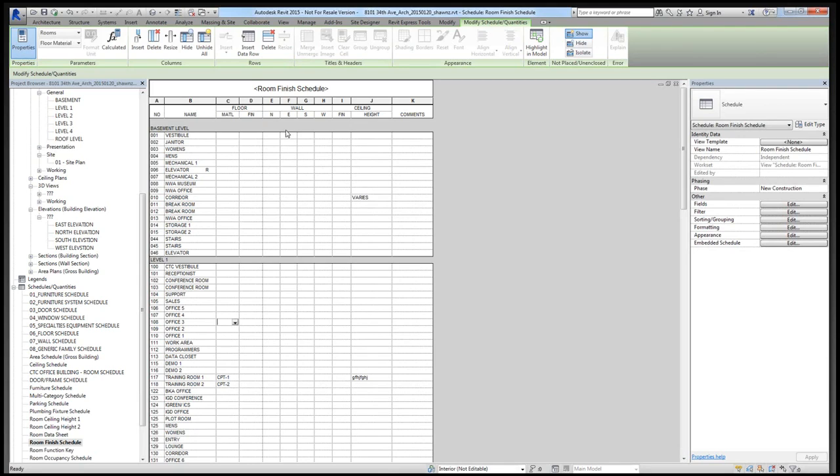And if I needed to, say, for each of my walls have a similar finish on each of the 4 walls in a particular room, I can't just autofill across very easily. I have to manually copy and paste values and manually click into individual cells. I can't hit enter or use my arrow keys. So it's not Excel. It's still editing back to the original room, but it doesn't have quite the functionality that Excel has. So what I'm going to do is take this exact schedule, and I'm going to kick it out to Excel so I can more easily edit it.